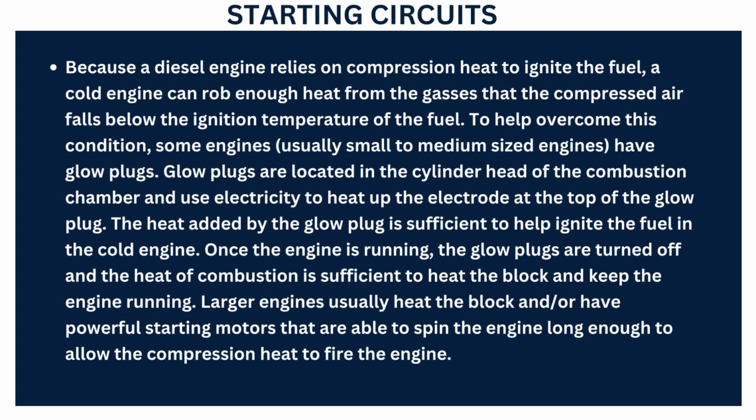Once the engine is running, the glow plugs are turned off and the heat of combustion is sufficient to heat the block and keep the engine running. Larger engines usually heat the block and or have powerful starting motors that are able to spin the engine long enough to allow the compression heat to fire the engine.